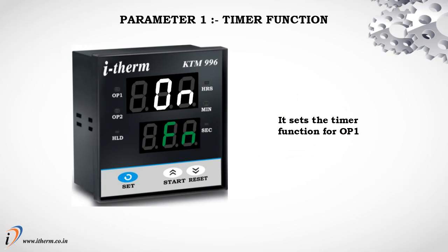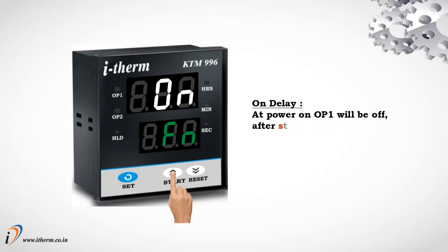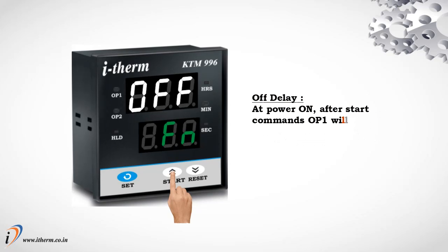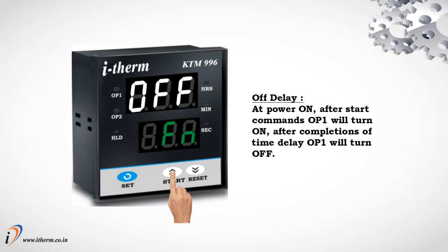Parameter 1, Timer function. It sets the timer function for output 1. On delay. At power on, output 1 will be off. After start commands and completions of time delay, output 1 will turn on. Off delay. At power on, after start commands, output 1 will turn on. After completions of time delay, output 1 will turn off.